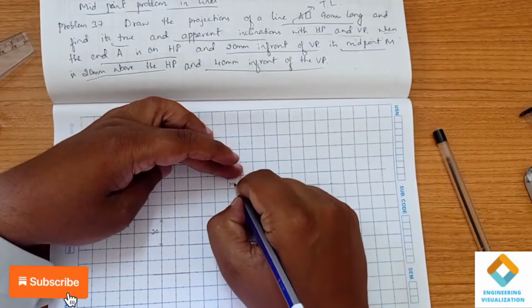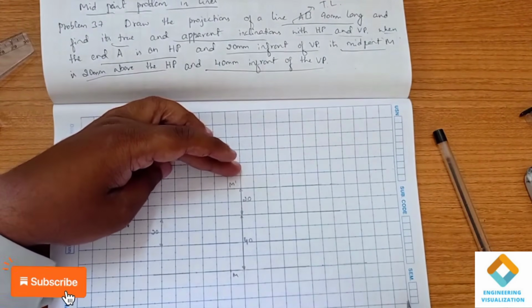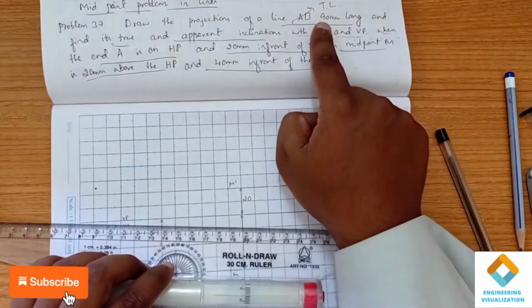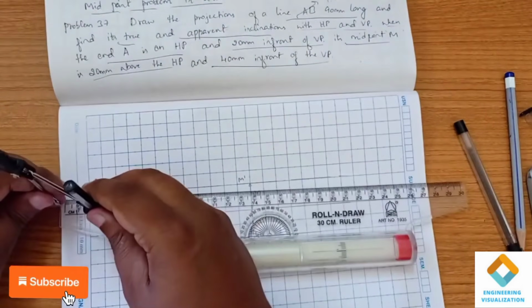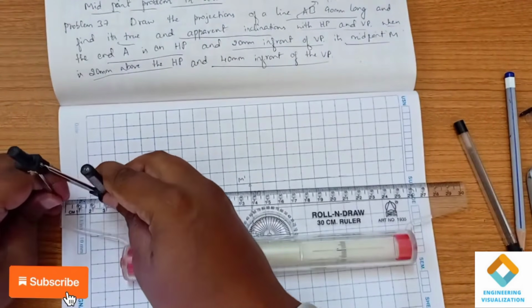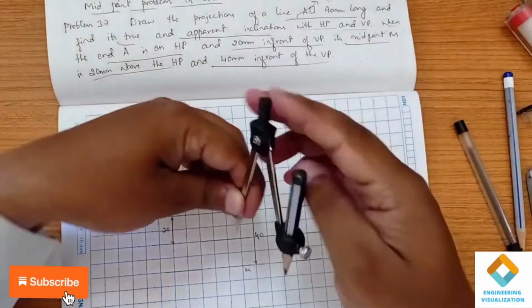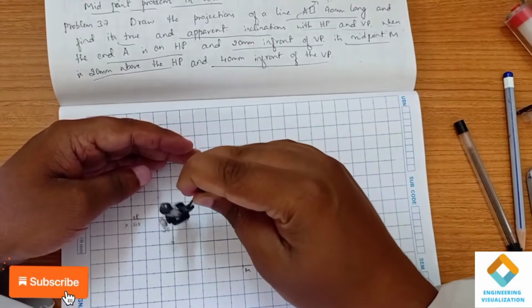This is M dash, and here we have M. So the middle point is drawn. Now we have the true length of the line, it is 90, so half means it is 45. So we have to consider a 45 length, and from this point on the XY, I'm cutting the first arc.